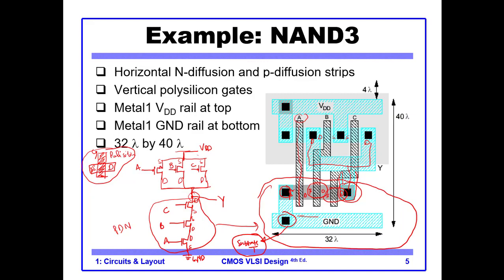You may ask how I select on which side is source and on which side is drain. Basically, if you look at the transistor, the drain and source are symmetrical. You can call one source and the other drain, it doesn't matter. It only depends on your supply. You connect the supply to the source, and the drain is used for interconnection, for drawing the current. So you can swap the source and drain.